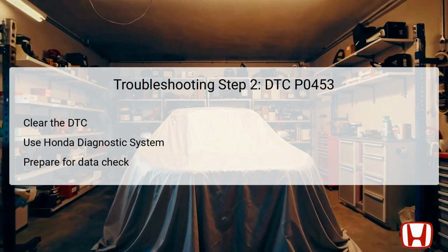After clearing the DTC, turn the ignition switch to the lock position, which ensures a safe working environment. Following this, you will need to remove the fuel fill cap before performing further checks. This process is important as it helps to eliminate any pressure in the fuel system, ensuring an accurate read from the FTP sensor in the following diagnostic steps.